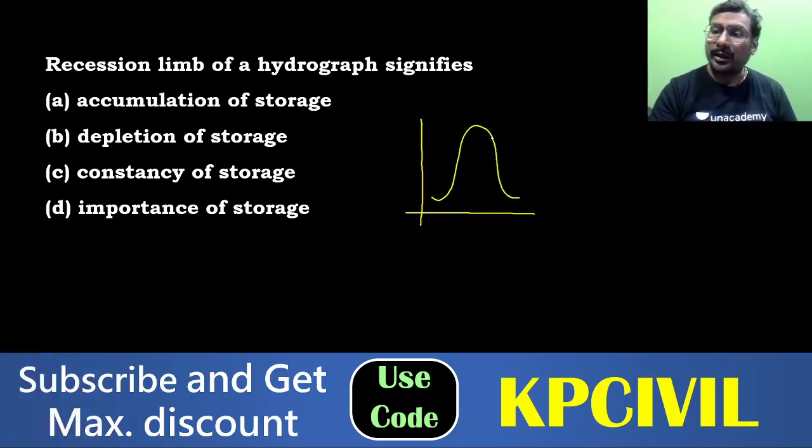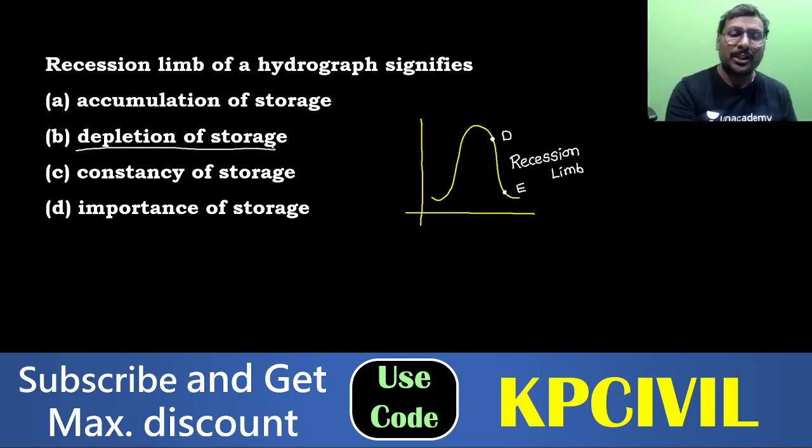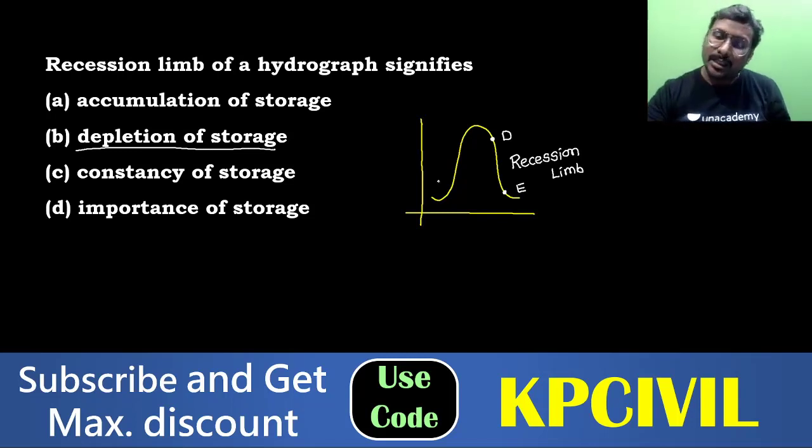Where is the recession limb located? This point D to point E. It is a recession limb, a falling limb. So what does it represent? A depletion. Storage is falling down. Accumulation of storage is shown by the rising limb. Falling down of storage is represented by the recession limb.